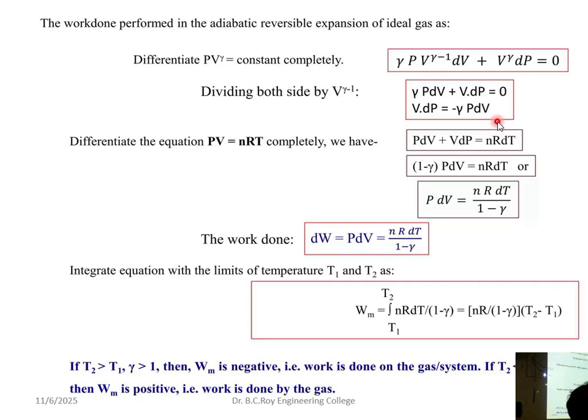But in case of isothermal, heat is always collected from the surrounding to keep the temperature constant. So heat is collected from the surrounding, and that can be converted to work. Total available heat is more, so work done also will be more, because Q and W are directly proportional.